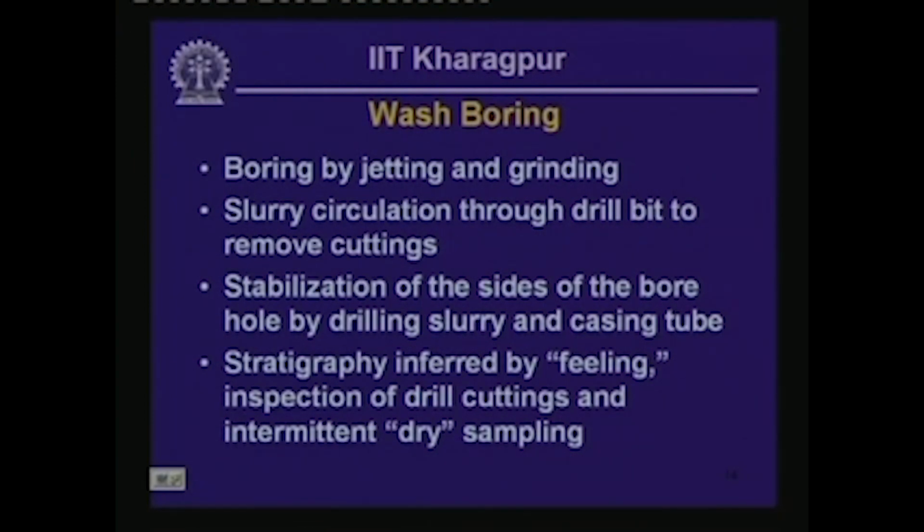First, we begin with wash boring. That is one of the simpler techniques for drilling a borehole in the ground. What is done here is that a heavy chopping bit is lowered within the soil layers, and this chopping bit is pounded upon the formation near the bottom of the borehole.